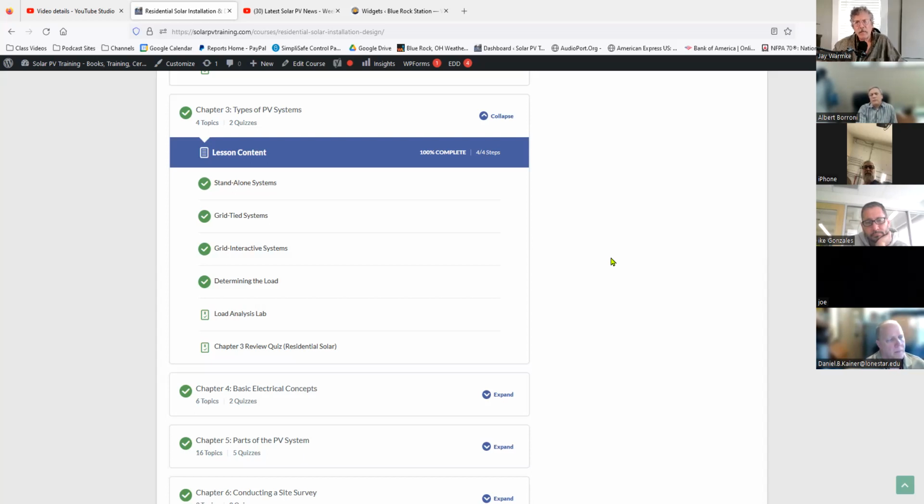They turn off because you don't want to be sending power back to the grid and electrocute a lineman. But part of these grid interactive systems is that they send a signal to the inverters, convincing them that the grid is still functioning, so they're still working. So now your array is producing if there's sunlight, you've got battery backup, and you're disconnected from the grid, so you can't feed back or island back to the grid. So now you're in standalone mode.